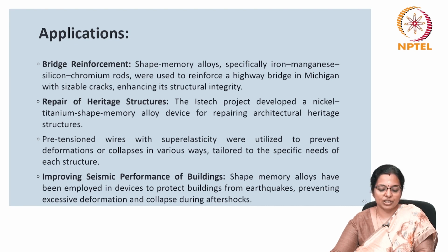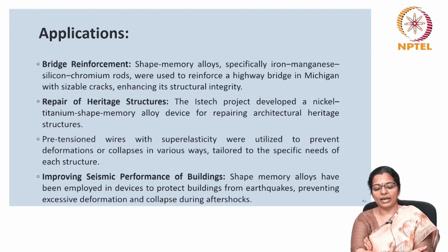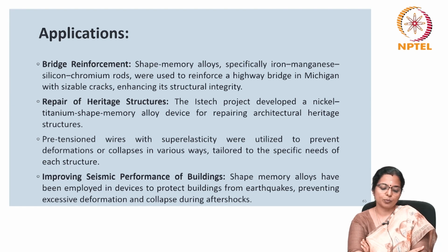Repair of heritage structures. The ISTEC project developed a nickel titanium shape memory alloy device for repairing architectural heritage structures. Pretensioned wire with superelasticity was utilized to prevent deformations or collapses in various ways, tailored to the specific needs of each structure.